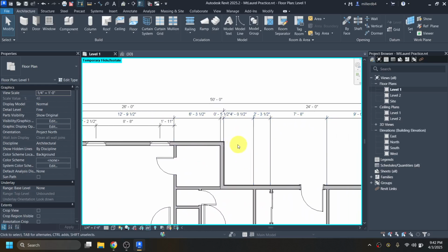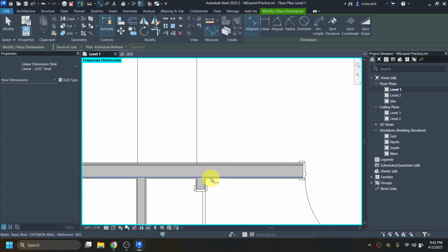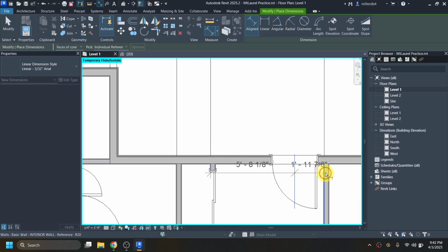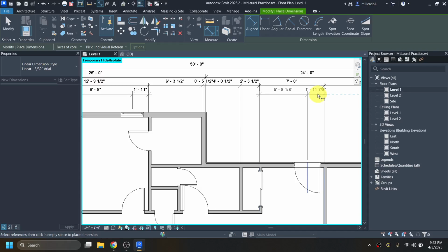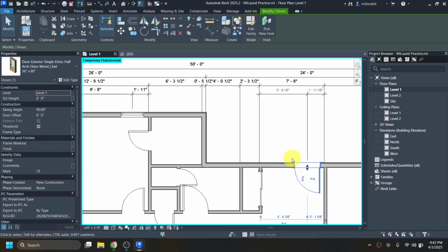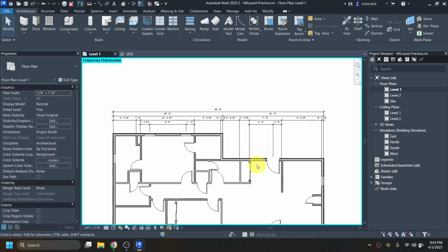We have another chain for this center of this door here on this wall. So again, that's going to be keyword shortcut DI from face of stud to center to face, and then I'll click up to place it, escape 100 times, and then I'll click on this door to change this number. So that is that side of the building dimensioned.